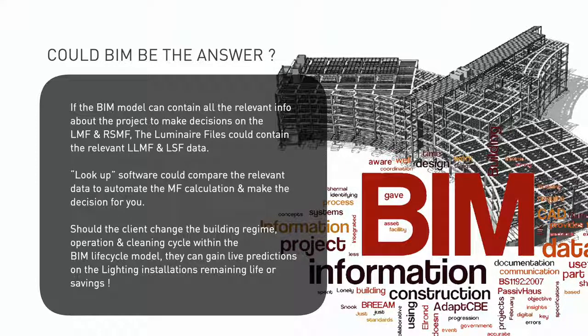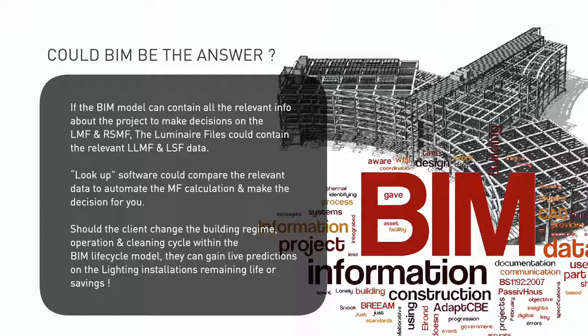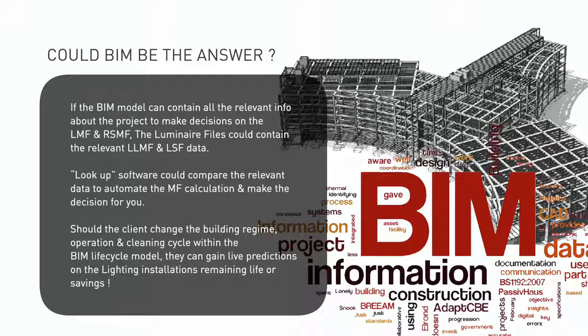The luminaire files that you then put into it with the Revit data could also contain the relevant information in regards to the LLMF and also the LSF data. So theoretically, you've got everything in there, including the project life and how you operate the building and what the cleaning cycle is. Everything is there potentially within the BIM model to be able to calculate a correct maintenance factor.